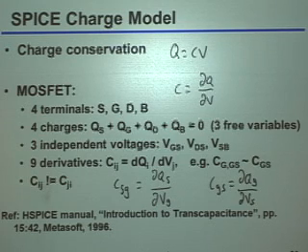Okay? Because, for example, changing the voltage at the gate certainly changes the charge in the channel, which changes the charge at the drain side of it. Whereas changing the voltage at the drain may not directly influence the charge at the gate. Okay? And so again, you'll actually see these things where one of them might even be negative or 0 and things like that. Nothing is wrong. It is indeed just SPICE being very meticulous about how capacitance is actually defined. Okay? Does this make sense to everybody?